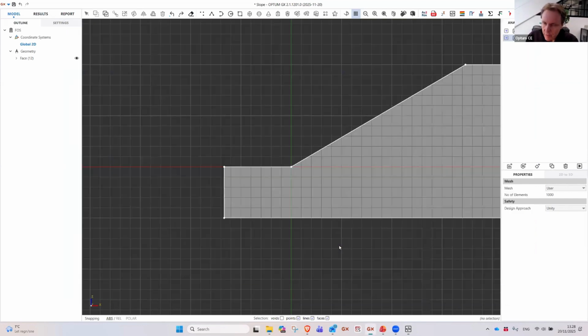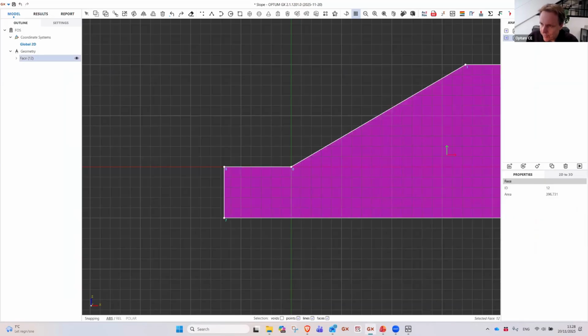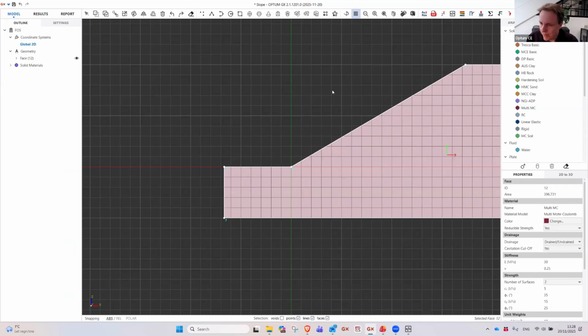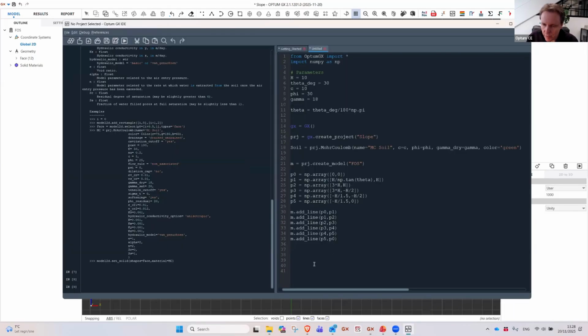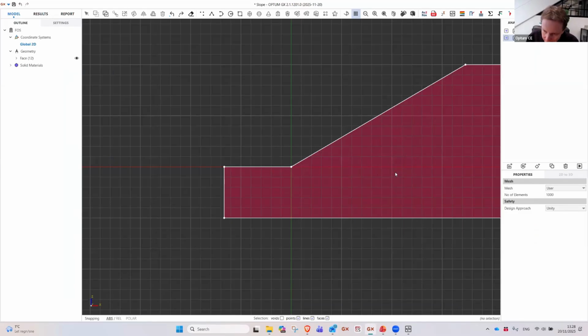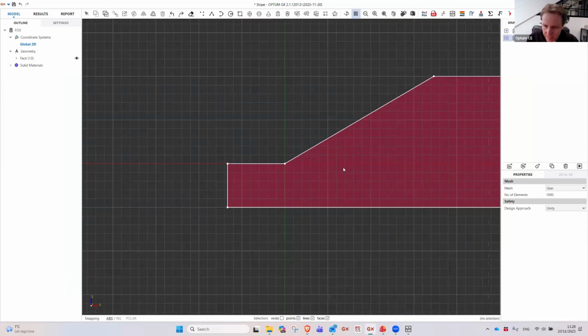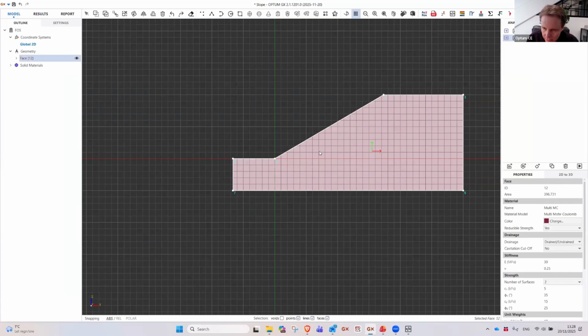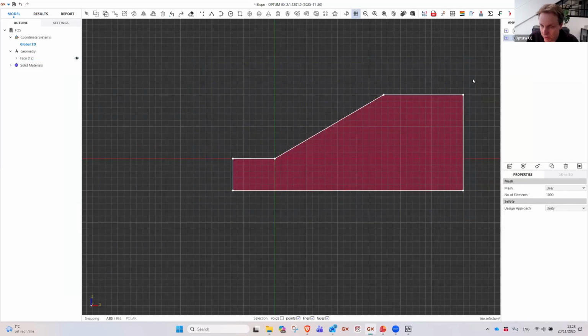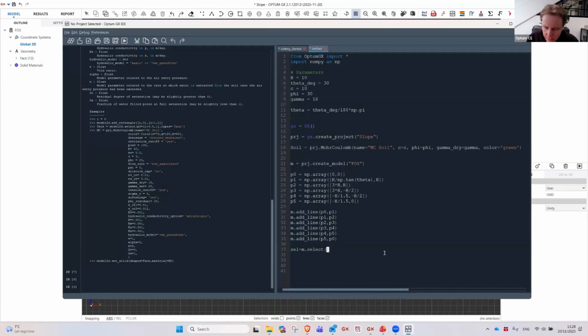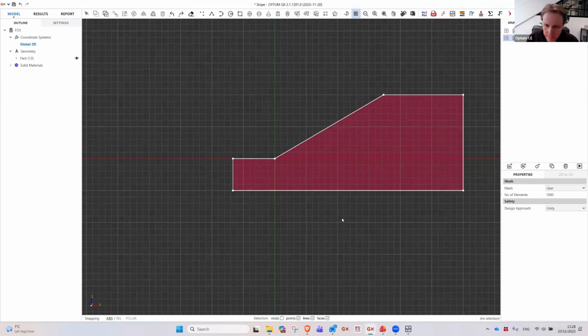And then in the user interface, the way we would apply a material is we would select this face and then apply the material. And through Python scripting, it's much the same idea. We need to first select the face and then apply the material. In that way, it really is one-to-one. So we have to do a selection. So I say M, that's my model, and then there's a function called select, and I then need to specify either a single coordinate, which corresponds to a mouse click, or a box like this, either a green or a blue box. But I'm just going to supply a coordinate, and the coordinate I'm going to supply is actually 0,0, which is right on the edge, but it will work.